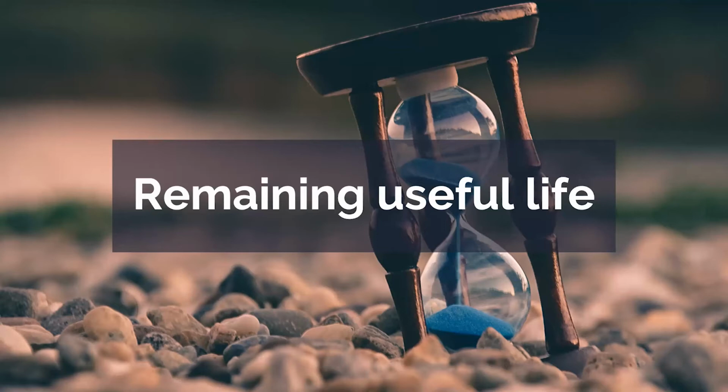There are a lot of factors that impact that, including installation, its maintenance record in the past, and what kind of elements it's in. Obviously, we're not going to cover all of the details to determine something's remaining useful life here, but just recognize that just because a PVC pipe typically lasts 50 or 60 years, there may be conditions where it only lasts 10 or 12, and we've actually run into that before.